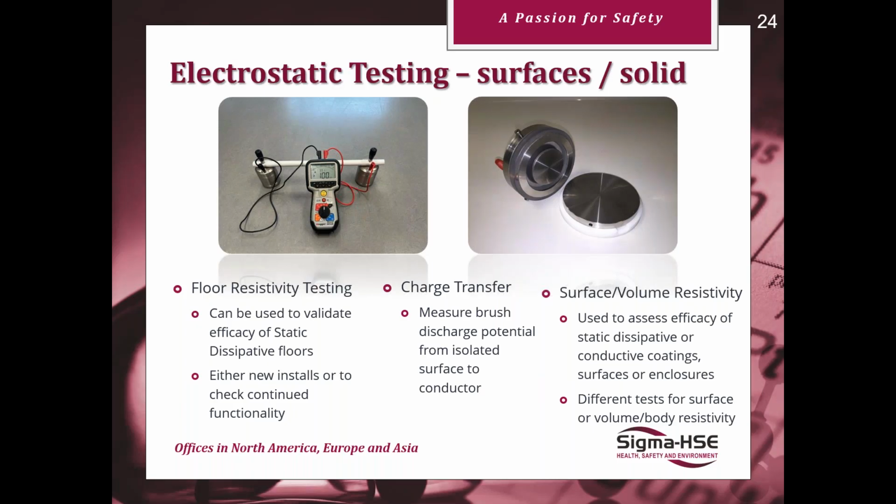Charge transfer testing can be used to measure brush discharge potential from isolated surfaces to conductors. So we can measure the functionality of certain overalls, PPE, and so on that operators might have to wear, and what kind of discharges this kind of clothing may give off.